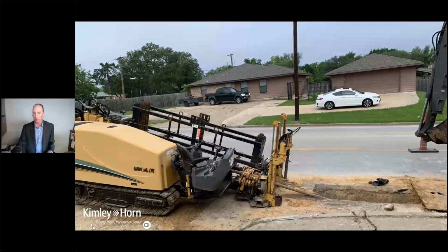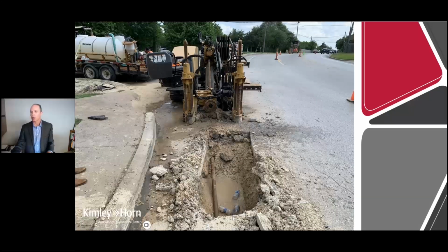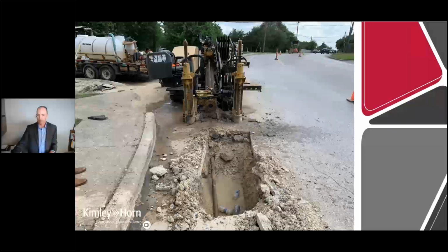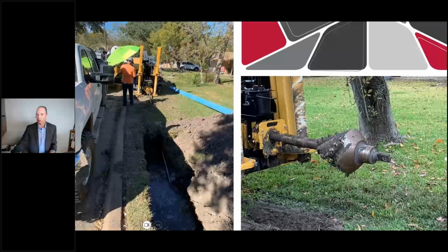that middle turn lane. So this photo here, you can see the traffic control up here on the right part of this photo, where they've got 2-way traffic utilizing that turn lane and the other lane, and then they close down the 1 lane for the HDD drill rig there. The next photo will show that, and there are some areas as we went further down, like I said, this is about 900 feet. As we went further down, they were able to, in some areas, install the water line behind the back of curb, which saved a little more space as well.